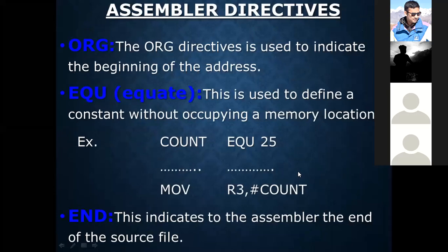Now there are some assembler directives. The ORG directive is used to indicate the beginning of the address. That also means that the ORG instruction loads the program counter content to 0000H.